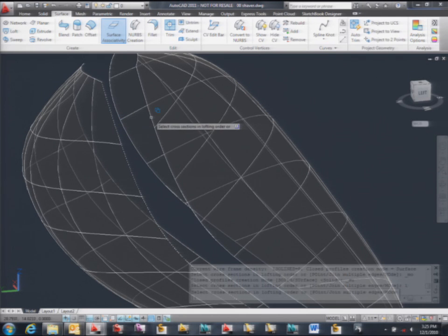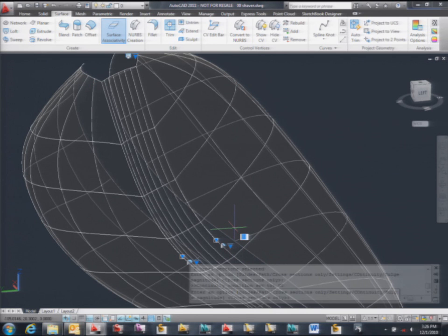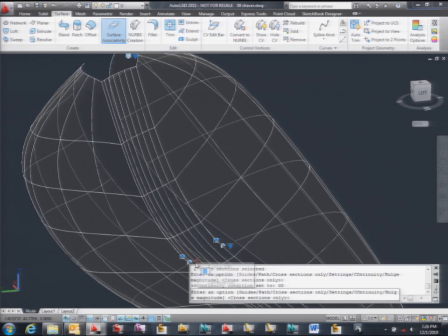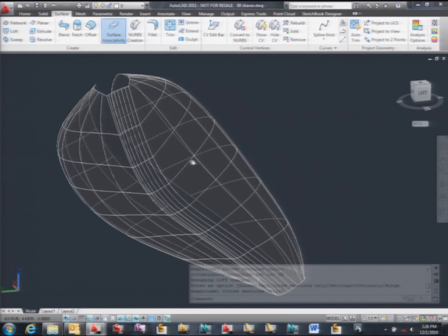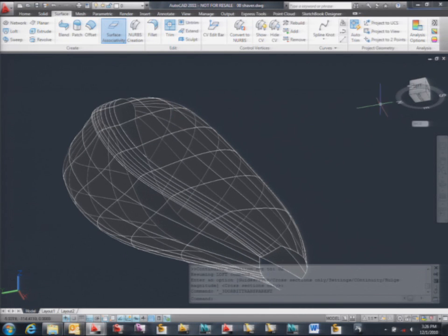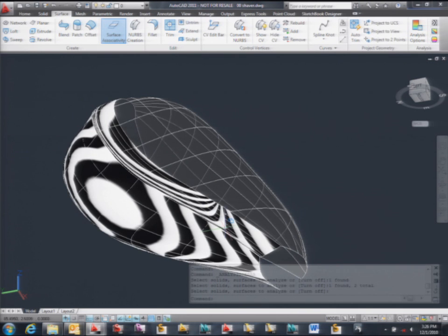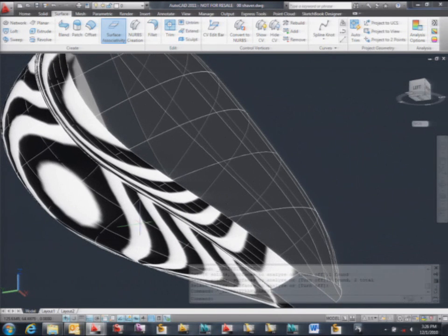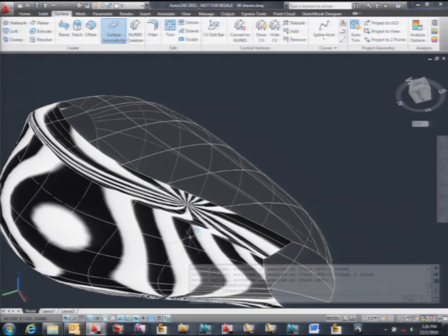For the second one, I don't care, because I may select the surface edge if I want, but anyways I'll give you that G0, because what I want now is that this side has G0, which is position, it's just getting there and nothing else, but I want G2 curvature on this side. I could even try and see how good or bad it is right now with zebra analysis. And you can see that it's kind of very abrupt, but still the stripe goes on. It passes by. You see, it just passes by.